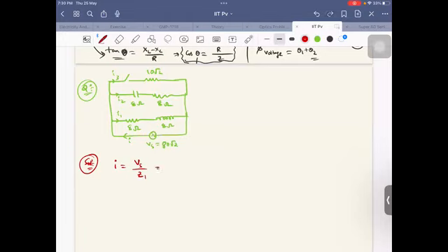So remember, if I take peak values, I'll take the peak value of the source voltage and the peak value of the magnitude of Z1. If I want RMS, I'll take RMS. If I want the complete value, I'll take the complete value of I and the complete value of Vs. I just want the RMS value of I1. So Vs RMS is 80 root 2.